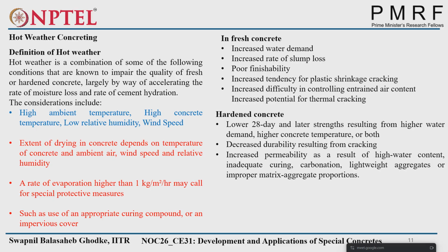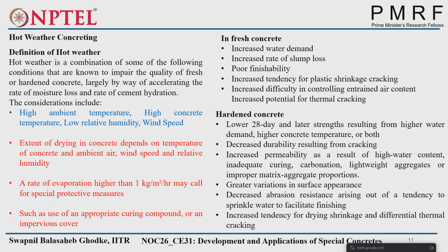So these are the impacts of hot weather conditions on the fresh and hardened properties of the concrete. Surface appearance will also vary because of the slump loss. We will not have the same workability, so there will be poor finishability. That's why greater variations on the surface of the concrete will be observed.